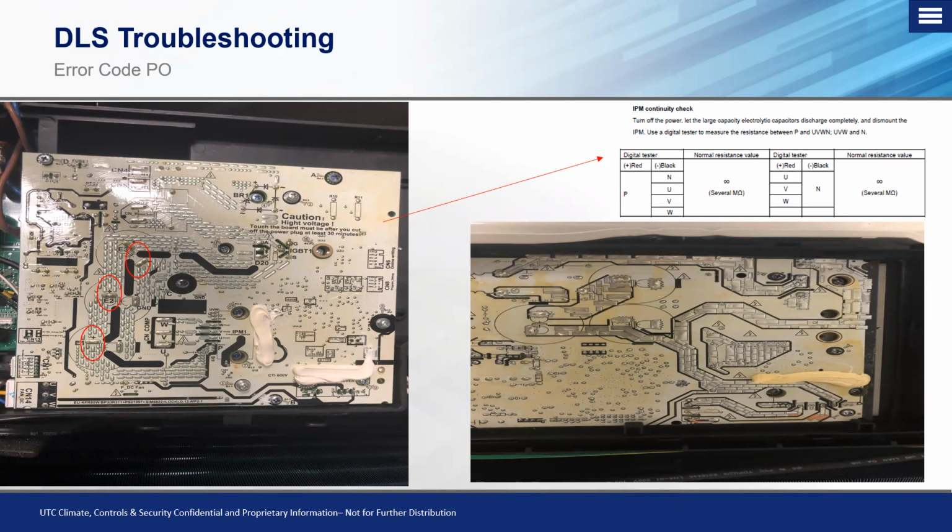Okay. If you have a higher incoming voltage on the AC side than you do on the DC side, so let's just say, for example, you have 232 volts AC and you only have 210 volts DC on the capacitors, you have an issue with your bridge rectifier, which we know is right here. It's internal to the board. You've confirmed that through a voltage reading, so you know to replace the board because the bridge rectifier is in the board itself and it's not external to the board.